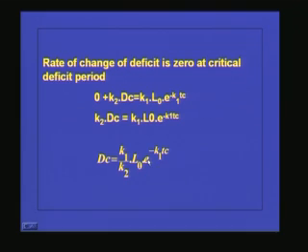So by using this dissolved oxygen model, we can find out the maximum organic load we can discharge into a stream, so that the dissolved oxygen concentration of the stream will not go below the specified minimum value. That is the most important use of this dissolved oxygen model, but there are certain disadvantages